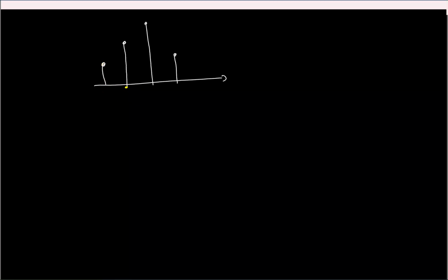Zero, let's say you are not adding any information, right? Let's say you want to do something better. Same. Basically you try to do the same, right? So it seems like the lazy and simplest thing to do. So, if this is a sample for one period, I'll hold the sample. Similarly, I'll hold the next sample for one more clock cycle and I'll do this. Okay, and this is called zero order hold.